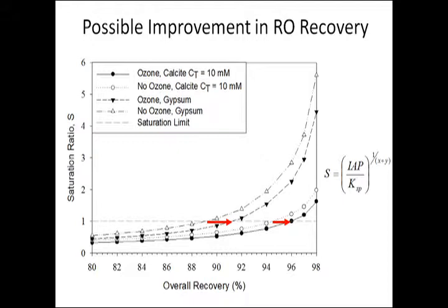reverse osmosis system. And this graph just tries to indicate that what would happen with that sort of treatment is that you could increase the amount of recovery that you get from your inland desalination system relatively substantially. And just an increase from, say, 85%, I think Ed said they got 83% in their system. If you can increase the result from 83% to, say, 90%, which doesn't sound like it's tremendously dramatic, what you've done is you've changed the amount of concentrate from 17% down to 10%, and that's a huge difference in terms of the cost that you have to spend for disposal. So what sounds like small increases in recovery lead to large savings in concentrate disposal.